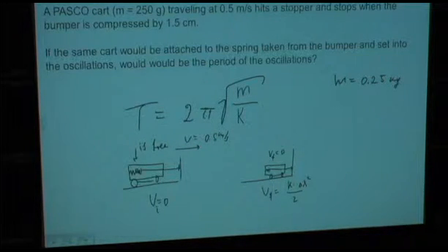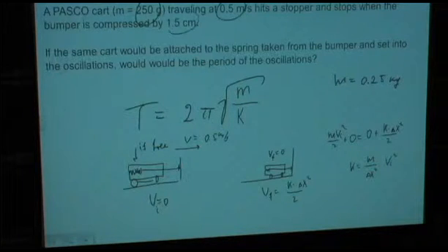And if we neglect any friction, m v initial squared divided by 2 plus 0 has to be equal to 0 plus k times delta x squared divided by 2. What we're looking for is k. So k will be equal to m over delta x squared times v squared. And we know m, we know initial speed, we know the compression. Questions, please?